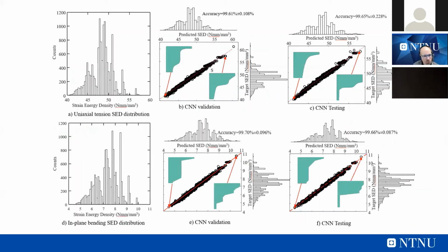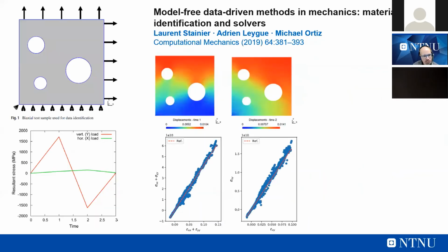This is the first estimation of what we are able to predict with very good accuracy using the SED in combination with a data-driven approach, with a convolutional neural network, for different kinds of notch geometries under fatigue loading. And of course, we are not the only ones working on this topic. The topic is not so bad if people from Caltech are working on it too. This work, for example, is from Michael Ortiz, dated 2019, where he applies a data-driven approach to this kind of notch components. Of course, a very simple geometry, but the message is very meaningful, because it is able to predict the final behavior of the component with different constitutive laws.